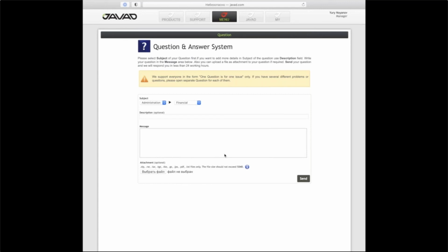Another variant is to import points in any format that GMT supports into the target for surface takeout, and GMT triangulates it and builds the same mesh of triangles. Then it can be used for surface takeout.